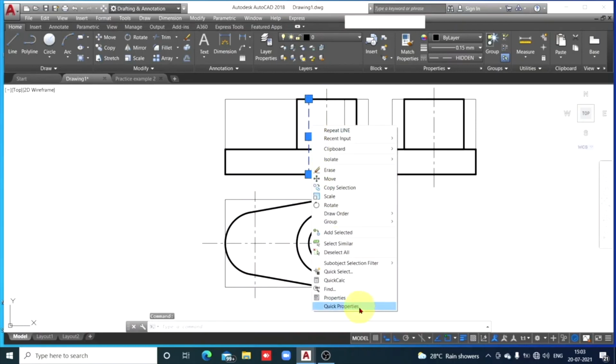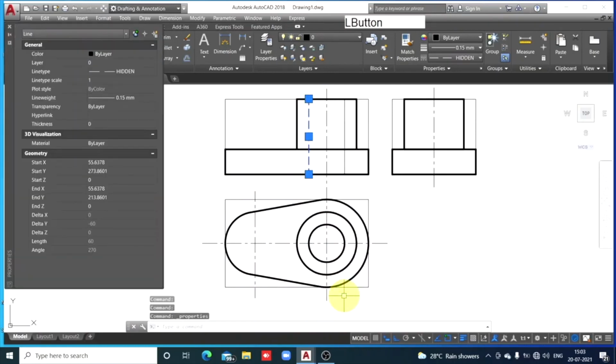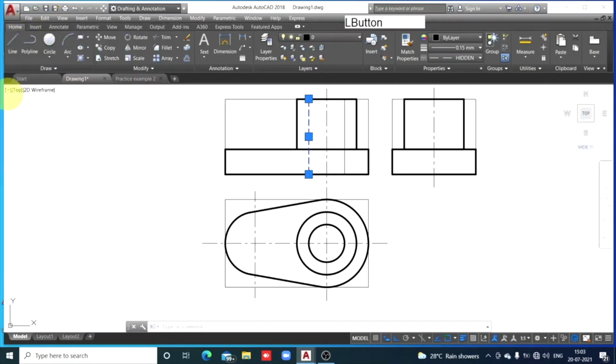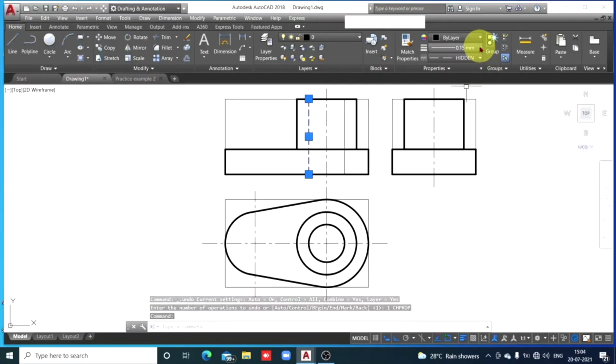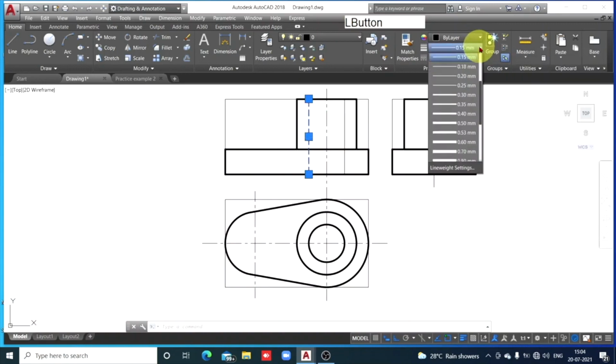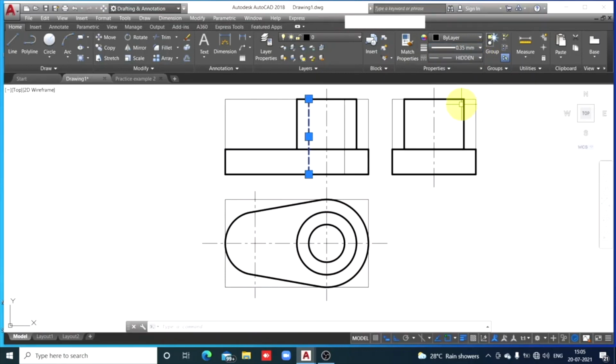Right click. Properties, and instead of 1 I'll make it say pointed 0.8. Enter and close this window. Escape. Now I'll select thickness for this line. Select the line, and for that hidden line it should be medium dark, so I'll make it 0.35. Escape.